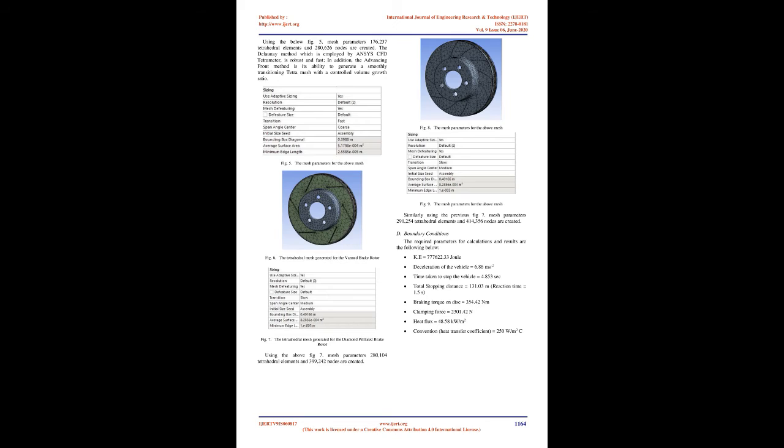The area between successive vanes forms a passage for air to flow. The number of vanes and the thickness of each element affects this area. A straight vane can be considered as a vane with infinite radius of curvature. Reducing this curvature effectively increases the available area and hence finds its use in a modern brake rotor design. The rounded slots on the brake surface sweep the gas and dust away from the wheels and clear the contact patch. Larger the vane thickness, smaller the effective exposed area.